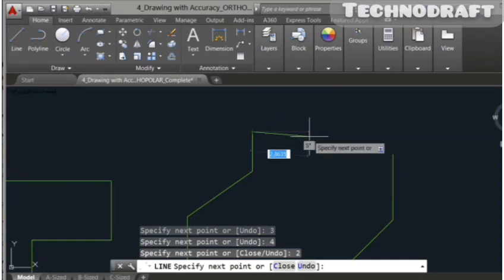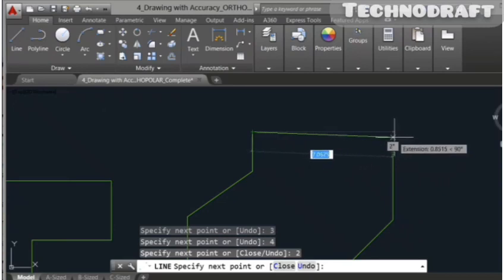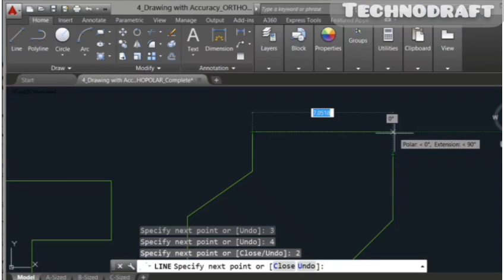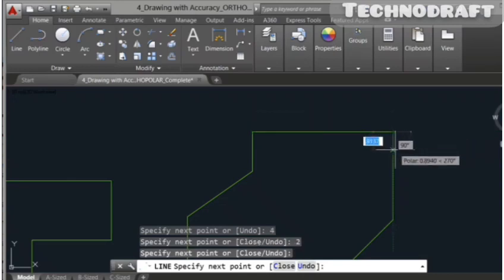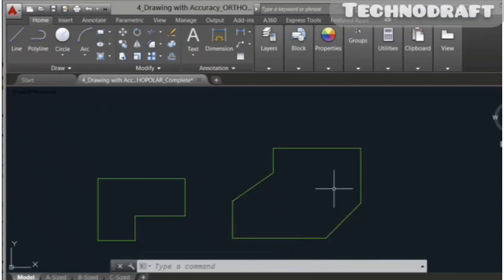And then I'm going to take that across this way. Now because I have polar tracking on, I can also utilize my object snap tracking, which is down there on the status bar. If I hover over that endpoint and just come up, everything will track together. There is the intersection, click that down at the endpoint snap, press enter to finish, and there is my shape utilizing both the 35 degree angle and the 45 degree angle that I set up in my polar tracking.